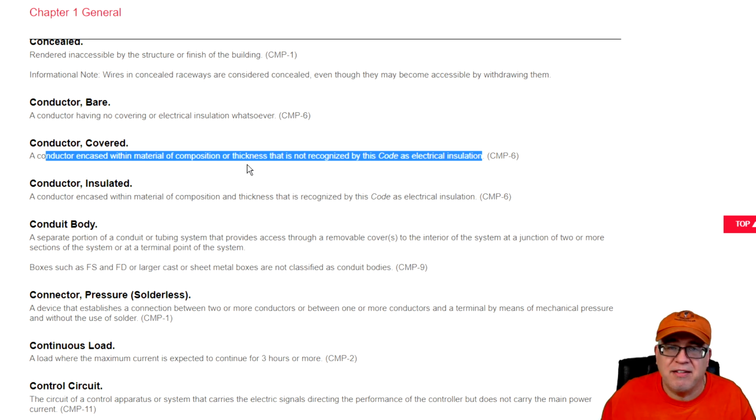It's important. Why is this important? Because there are some aspects, for example, when you're dealing with Article 680 for maybe hot tubs that are indoors inside of a building, or maybe portions of a pool wiring system that's inside of a building that allows you to use Chapter 3 wiring methods, which might allow you to use a covered equipment ground rather than an insulated equipment ground. And it's important to you to understand what covered conductors mean. And that's just a great example of that application, okay?